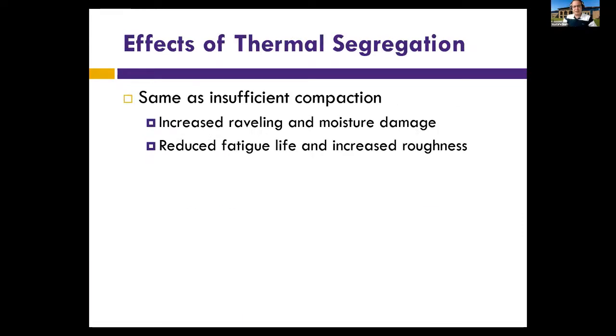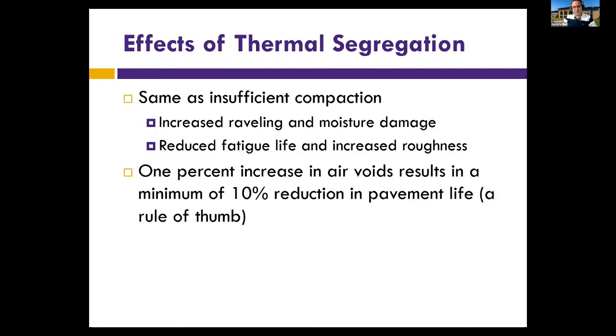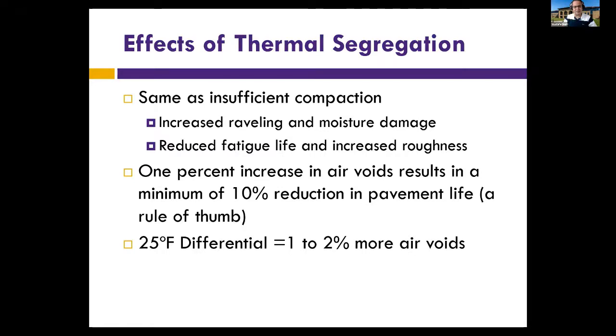So the effect of thermal segregation is the same as if you are not compacting your mix. So that's a very bad thing. It can increase raveling. The mix is more permeable, so it increases moisture damage. It will reduce the fatigue life, and it will increase the roughness. And they found that, generally speaking, an increase in air void of 1% will cause a 10% reduction in pavement life. So that, as I said, is a very significant factor.